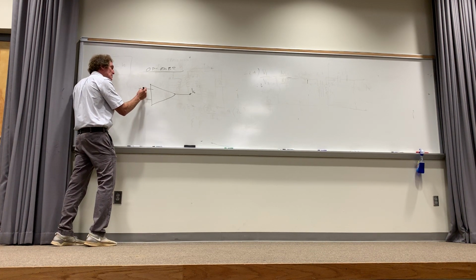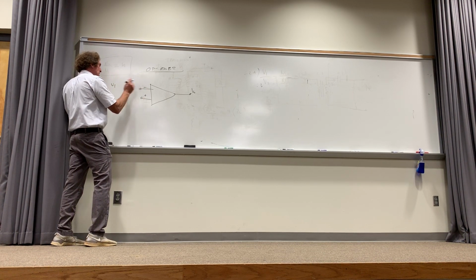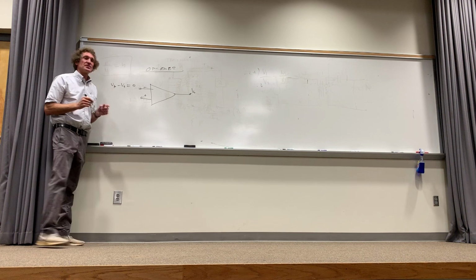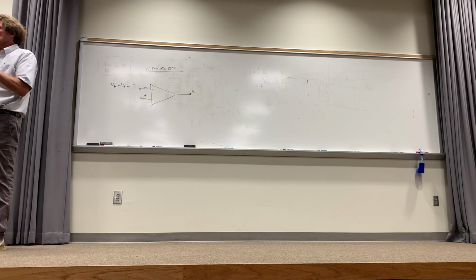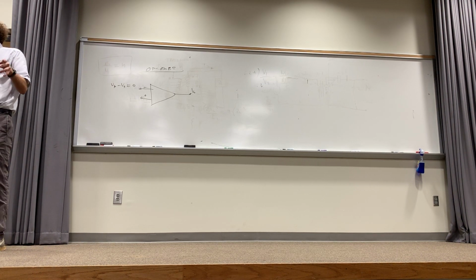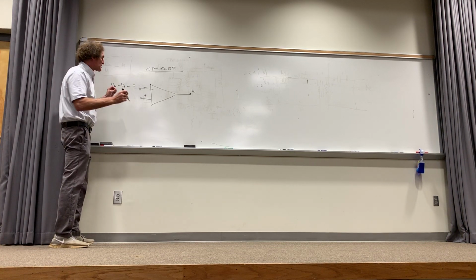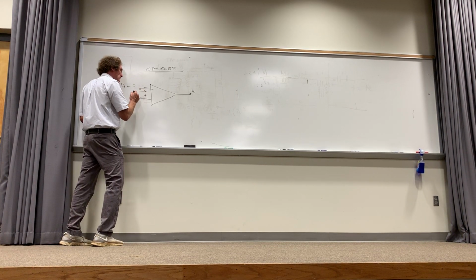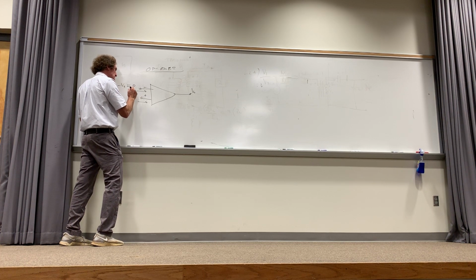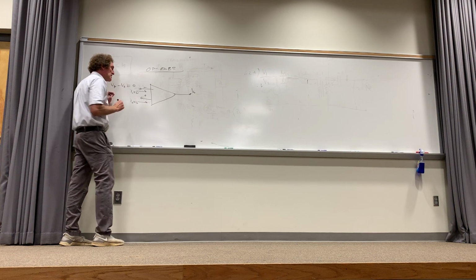There is no voltage difference. So if we take V minus on the minus terminal, minus V plus on the plus terminal, it's zero. There is no voltage difference between these input terminals. This is going to bother you. Not only that, because of the magic of these electronics, it never allows current in here. So I minus is equal to 0 and I plus is equal to 0, which seems stupid.